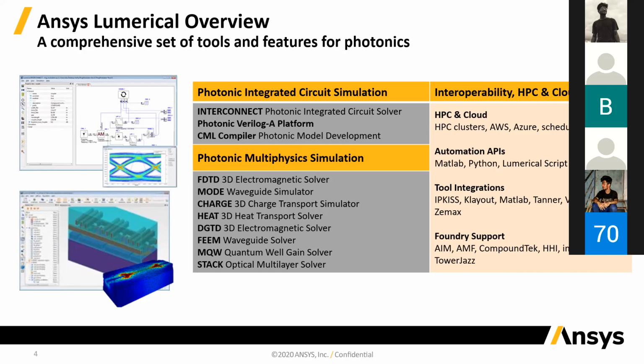And when you run photonic circuit simulation, you need compact models for all the individual elements in your circuit, so that you can include their behavior in the circuit simulation. So that's where CML Compiler comes in, which allows you to create those compact models for your simulation. And on the interoperability side, you can see there are lots of topics here. If you're running very large simulations, then you can run your simulations in cloud. And so that's what this first category is about.